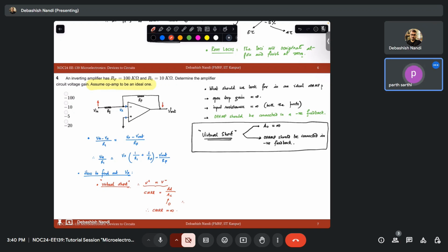Decreasing. So this is your negative feedback scenario. Now suppose you are pushing your signal at this point, and somehow by increasing this value, you are increasing your V out, and that same V out you are pushing into this positive terminal again. So your negative terminal remains the same while your positive terminal keeps increasing. So the difference between V minus and V plus will keep increasing, until it hits the oscillation limit. Then it will start to oscillate.